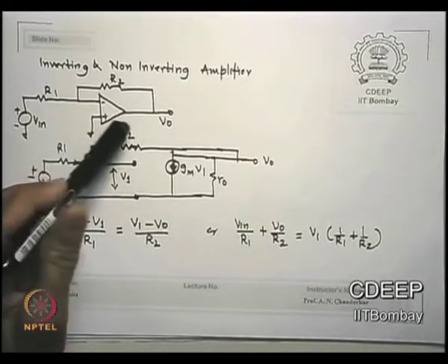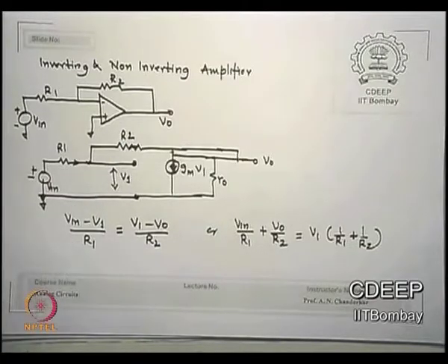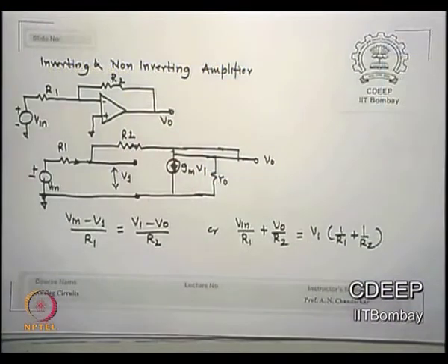I will not solve this problem directly, but can you think which kind of feedback circuit this is? If the output is made zero, will any feedback come? It will not come, right? If Vo is made zero, then there is nothing in R2, right? That goes to zero. What does that mean? What is being sampled? Voltage has been sampled. So what kind of sampling is it? Shunt sampling, is that correct? At this node, what is being summed up essentially?